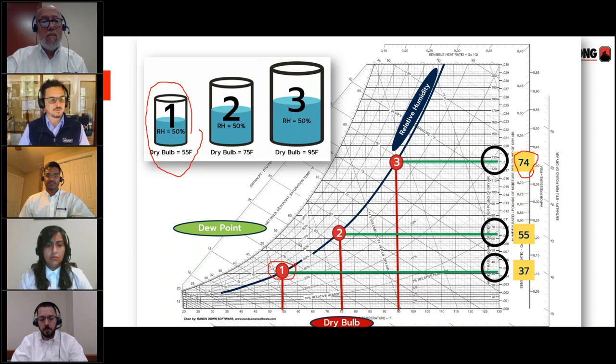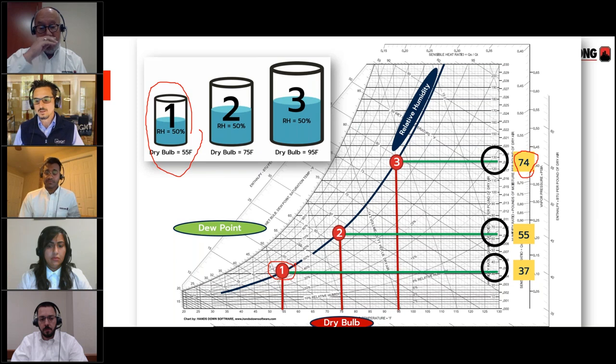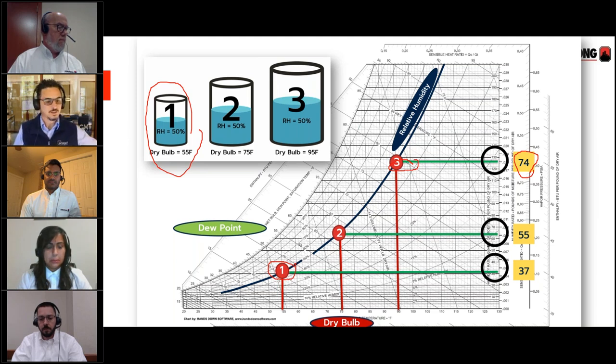Let's say you had a makeup air unit and you were initiating the dehumidification mode on relative humidity. And you said, anytime it's over 55% RH, I want to dehumidify. Well, this state here, you would not be dehumidifying if you follow that set point, and it's an extremely humid day. So that's why relative humidity is a little bit hard to use in certain situations. It doesn't really tell you the true nature of what's going on with the air.